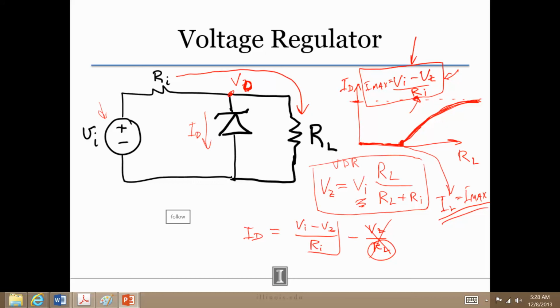but you know, at some point, of course, our Zener diode might have some sort of a maximum current rating, so that we don't burn it up. Maybe we cannot say 100 volts and regulate it at 6 volts V Zener and do it with a small input resistance in such a way that we get a ton of current through the Zener, because we might burn the real device. Okay, but on paper this is what it looks like. All right, so you can think about it this way, and then we'll do the IV characteristics of this as well.